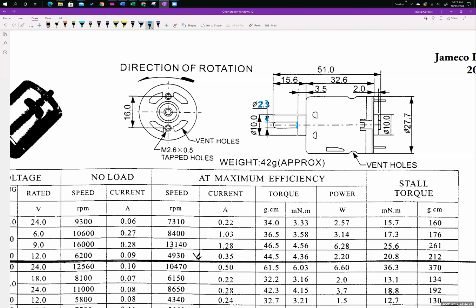You can see the arrows here like that. And then you can extrude it out to be whatever that dimension is. So it would actually be this 15.6 millimeters minus this 3.5 millimeters. And that'll give you the distance that needs to be extruded.